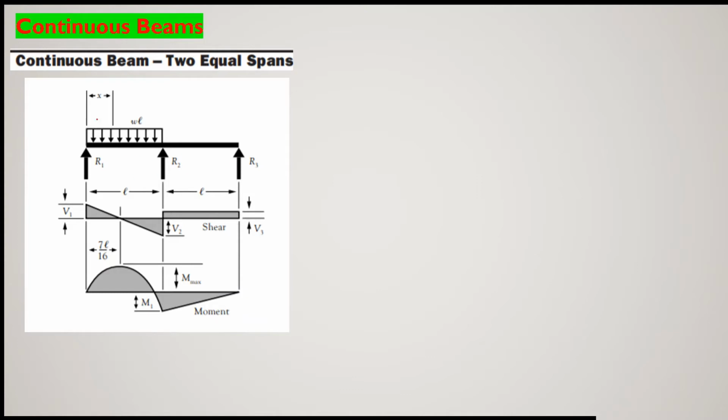Now again continuous beam can differ in the form of the span length. Now if you see here both the spans are of equal length. They can be of different. So it hardly matters, when the span length changes, then bending moment diagram will change. Now here you can see that only the left side of the span is loaded and the right side of the span is not loaded. That means this portion of the beam may have to be designed for only self weight or minimum load.